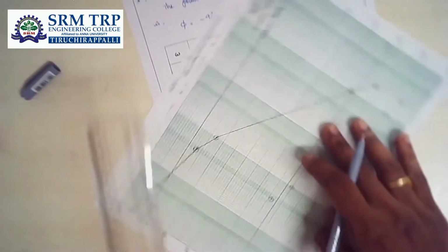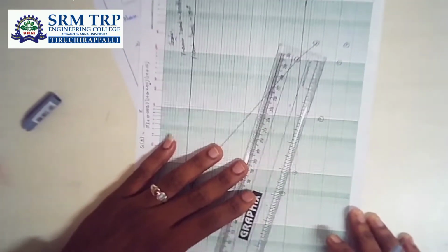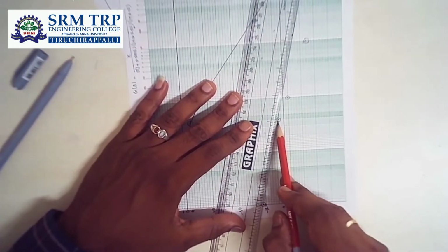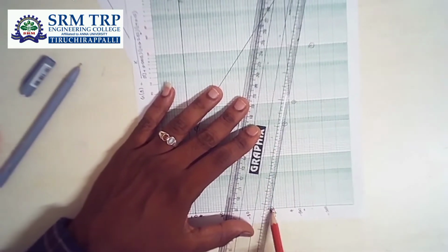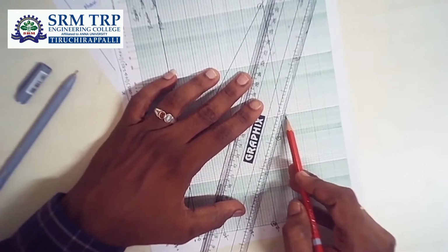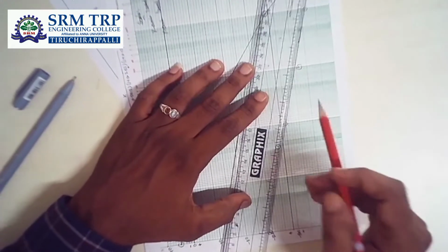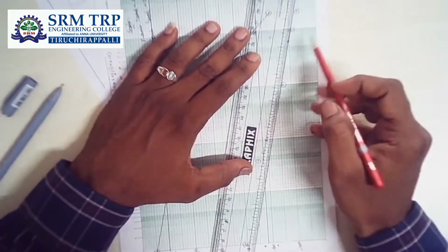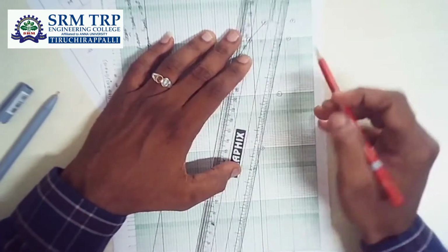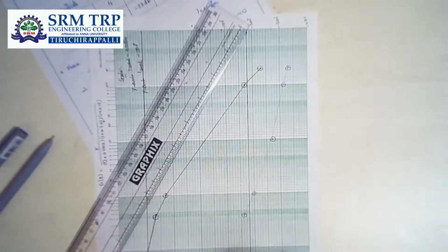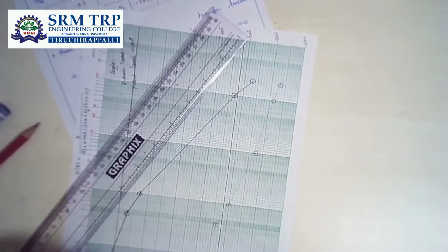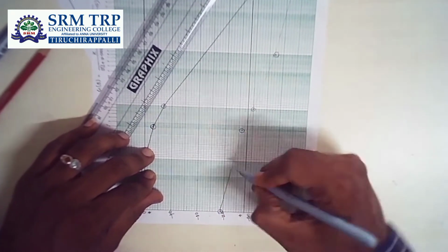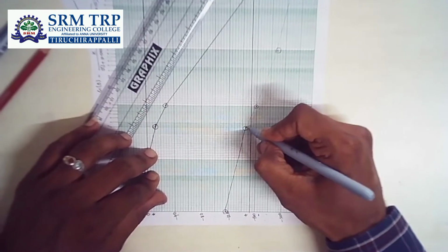Now I have sketched all the coordinates inside the phase plot. What we need to do is join all the coordinates using a scale and a pencil. You have to use a 2H pencil so that it should be very smooth, and we should not use a scale for connecting the phase plot coordinates. To have a smooth curve, we should use only freehand to connect all the coordinates. But I am using a scale, and just see what I am going to do after this. So I have connected all the coordinates very lightly. Now I will sketch over this line. I am going to draw the line using freehand.